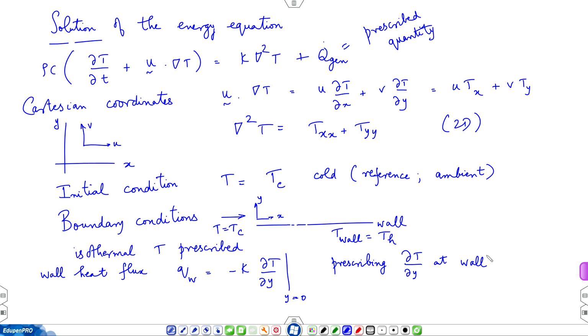So, you have to be aware of what calculation is in progress. So, I may write here Kf. This material has a conductivity Kf, viscosity mu. Why do you need viscosity? Because you have to solve the mass and momentum equations. That velocity goes into solving the energy equation.